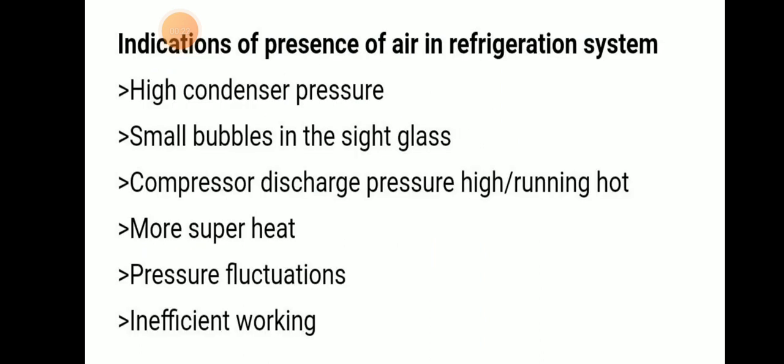The indications of the presence of air in refrigeration systems are high condenser pressure, small bubbles inside the glass, compressor discharge pressure high or running hot, more superheat, pressure fluctuation, and inefficient working. So here are some of the indications of the presence of air.